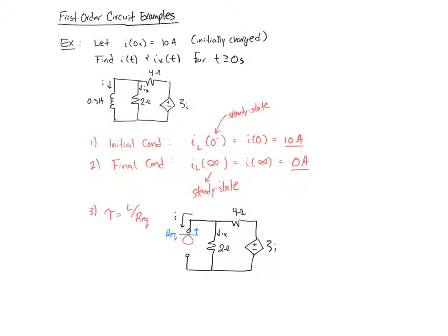So I'm going to connect an independent source to those nodes. I'm going to actually make it go downward and call that 1 amp. I'm going to make that downward because I just becomes equal to 1 amp here. And this voltage source becomes 3 times 1, or 3 volts. Okay, so now to analyze this, what we're looking for is the equivalent resistance, given as the voltage V_SD across that current source divided by the amount of the current, which is 1 in this case.